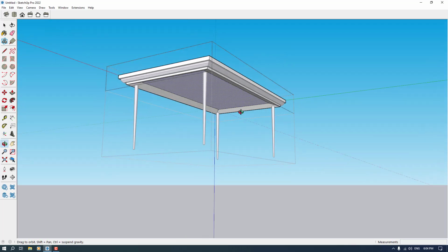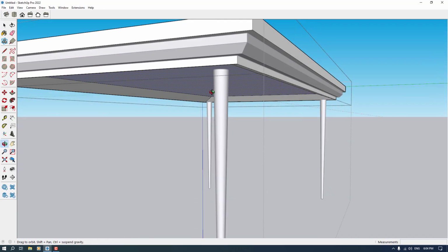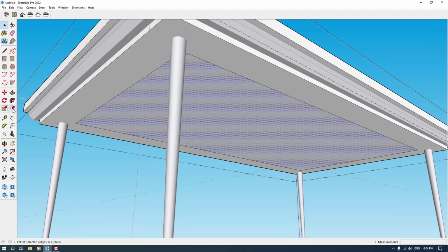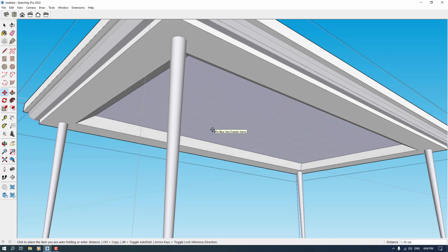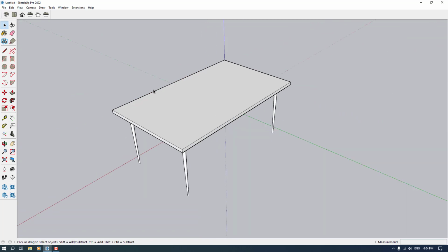As you can see, it's really good, but our holders have some distance between the real surface. For this reason, I'm gonna add another offset for it, about 3 centimeter, and now I want to bevel it like that. Alright, now it's much better than the past.